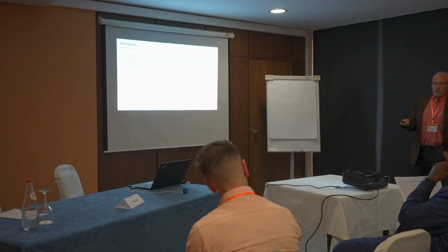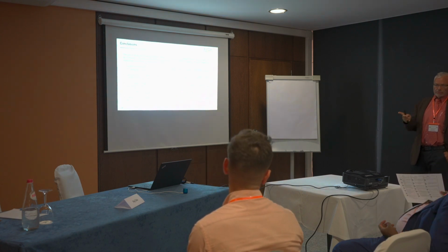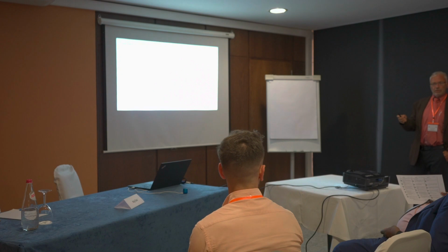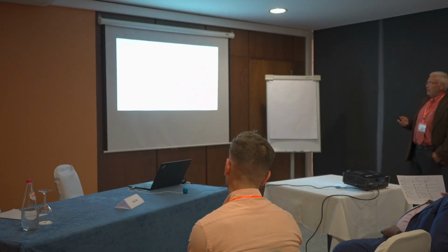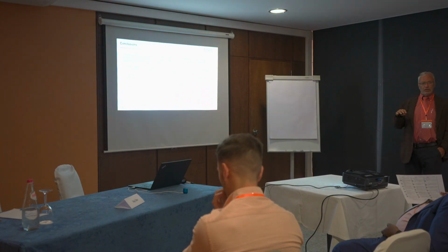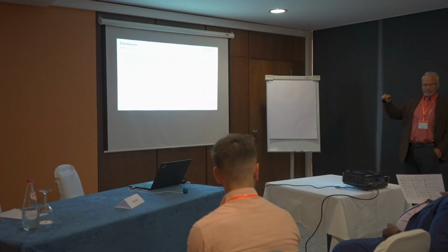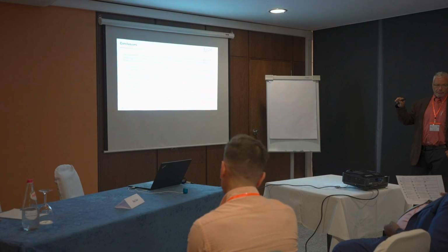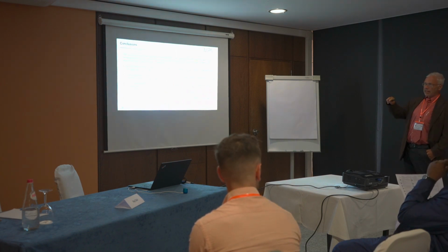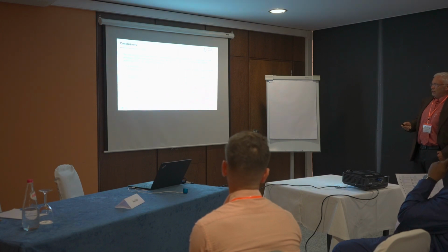S690, the results were at very low temperatures, and the arrest temperature was nearly the same as for the upper B material. So this might be the reason that we also found only a few of these local arrests, not so many as for the other material.